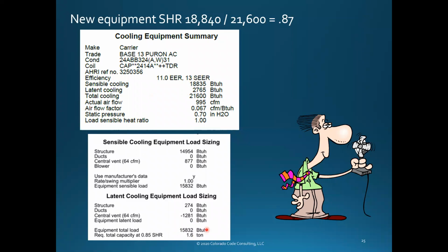You might have said, that's just too close. If I were just to look at the performance chart, that 800 CFM, it's not giving me almost 16,000 BTUs of sensible. But when I realized that I'm increasing the fan speed not only for altitude, but I've got all kinds of excess latent, it's not like the 21.6 disappears.